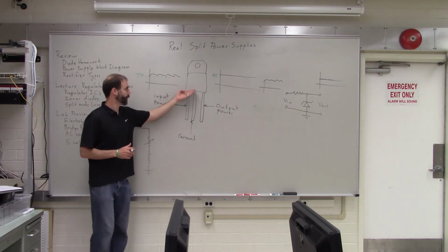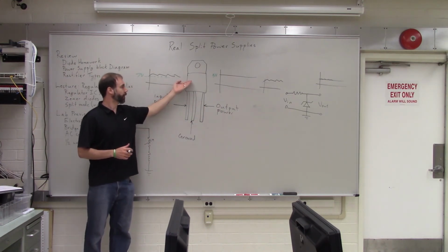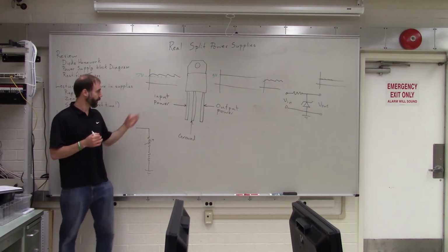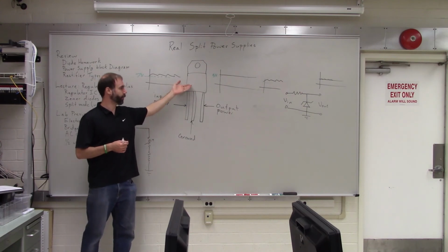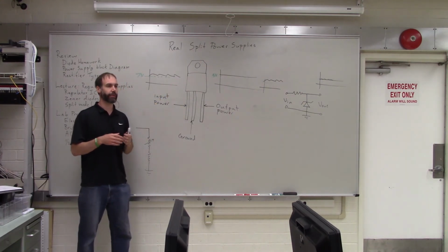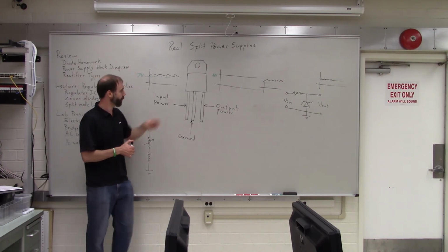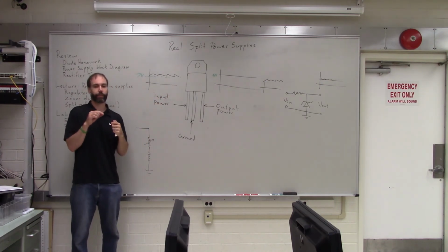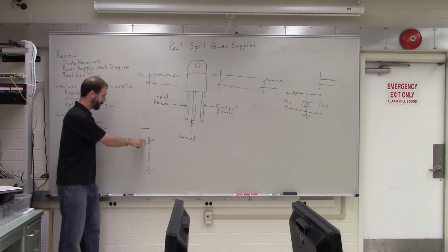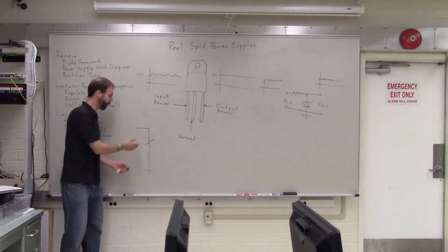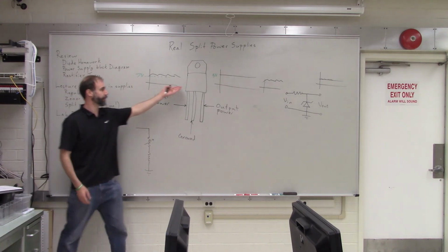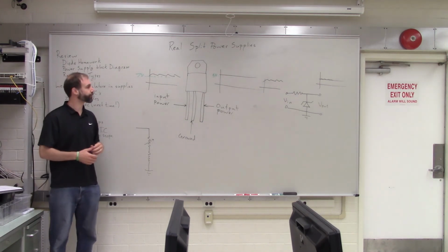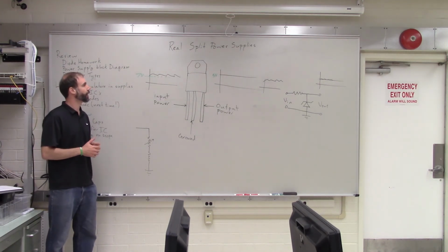So I think I mentioned inside of here, the regulator needs to know what voltage you're trying to get out. Normally, it figures that out with a little tiny Zener diode. So if you are trying to get 5 volts out, there's a little tiny Zener diode that's 5 volts built in there, and it uses that as the desired signal, and then it adjusts this variable resistor up or down till the output voltage matches that output from the little Zener diode. So that's what's happening there.